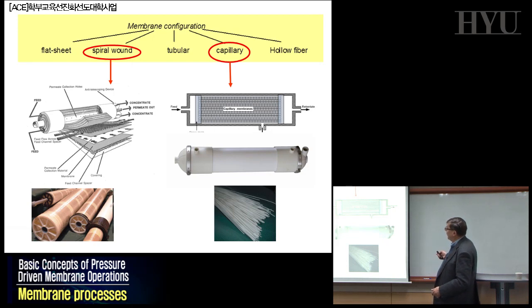If you are using hollow fiber from the same material, you don't have 7 square meters. In the same size, you can have 500 square meters, 1,000 square meters. Hollow fiber can be like hair. Today there are machines where you can spin fibers like hair. That means 60 microns, 70 microns, with a hole inside. And the solution is going inside and something permeates. That is gas phase or also liquid phase.